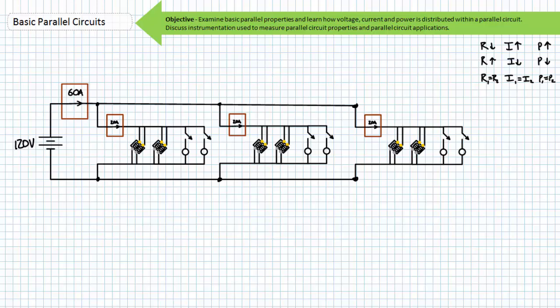Returning back to our residential electrical distribution example, consider the predictability offered by proper functional isolation. If the breaker that says all kitchen outlets is off, every outlet in the kitchen should be off. If there's an outlet in your kitchen that's actually part of the bedroom circuit and the breaker servicing the bedroom branch circuit is closed, that outlet in the kitchen is live. Do not assume everything you see in one room is part of one circuit.